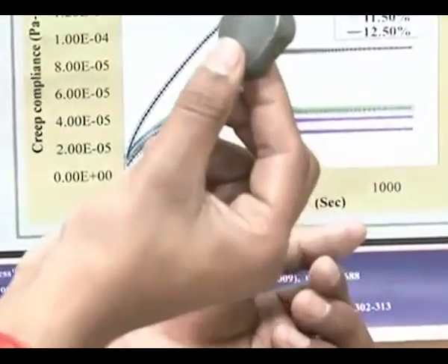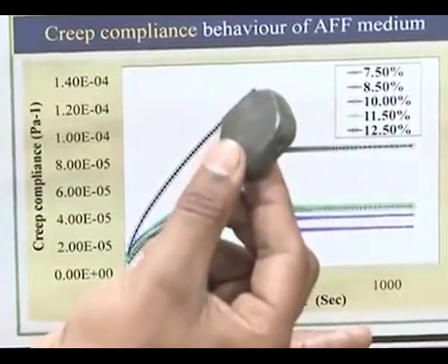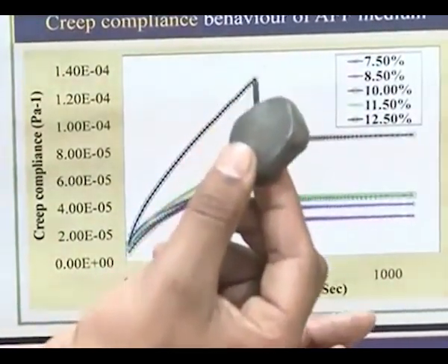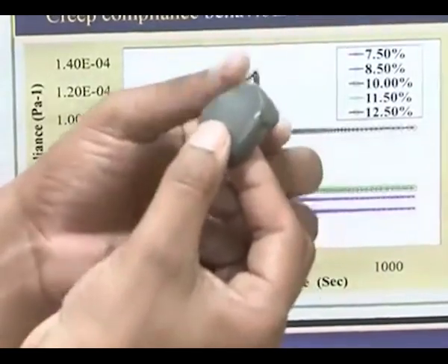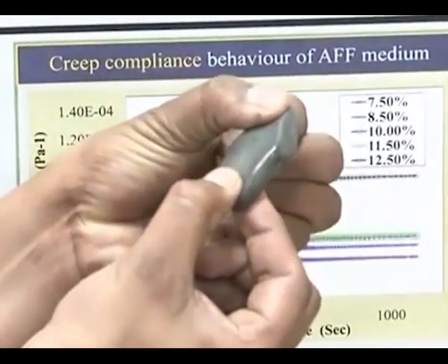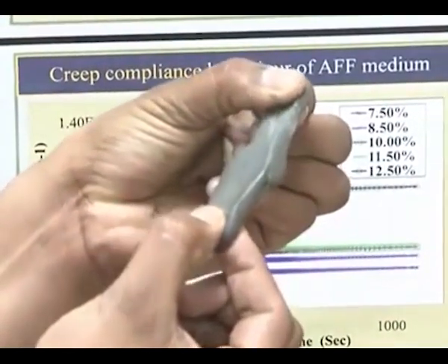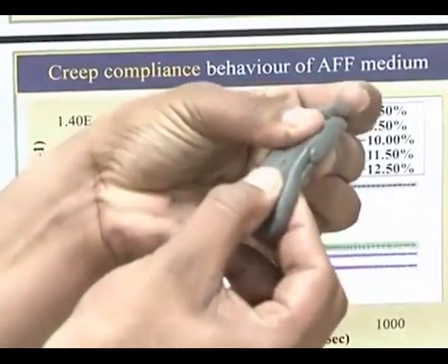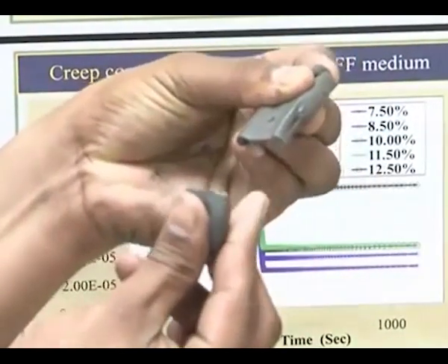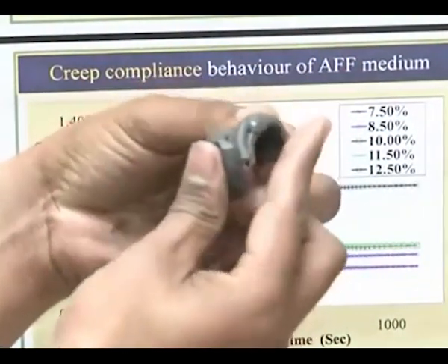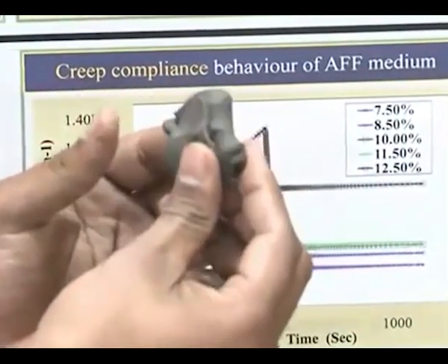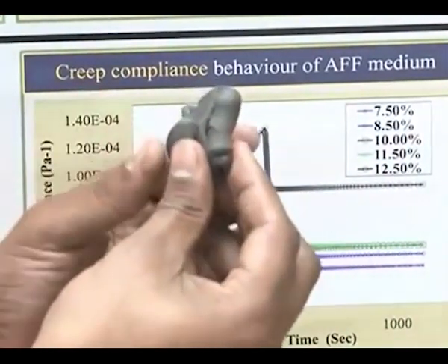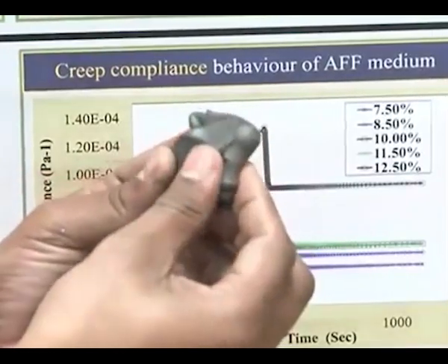This is the polymer rheological abrasive medium that we have fabricated in-house. This has special characteristics. If you stretch it, it will continuously stretch. If you pull it suddenly, it will break into two parts. It also has self-deformability and better flowability. All these special characteristics are imparted.